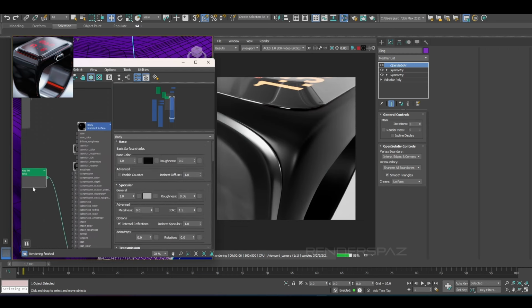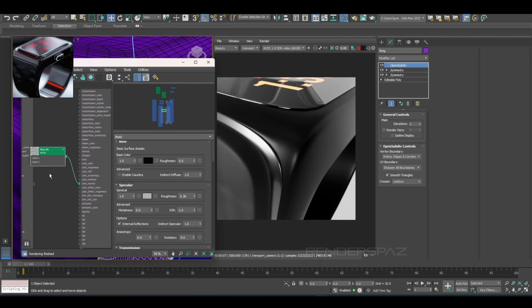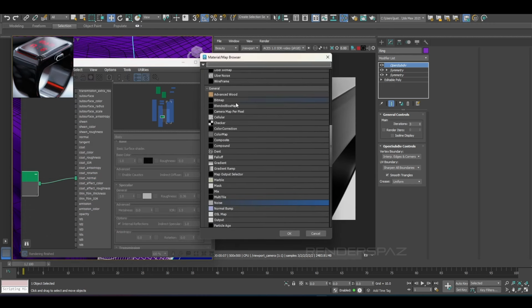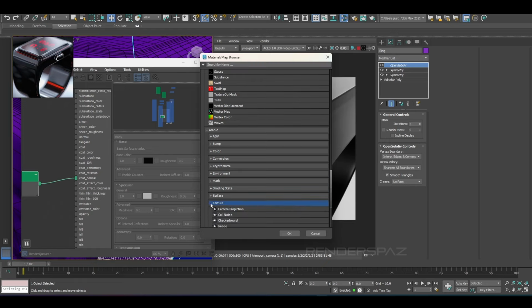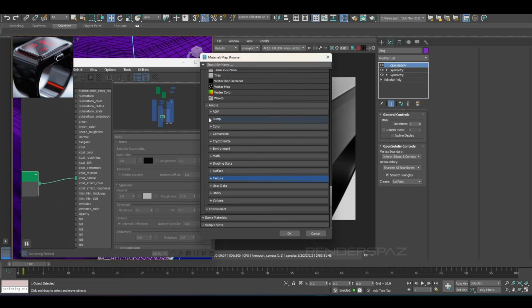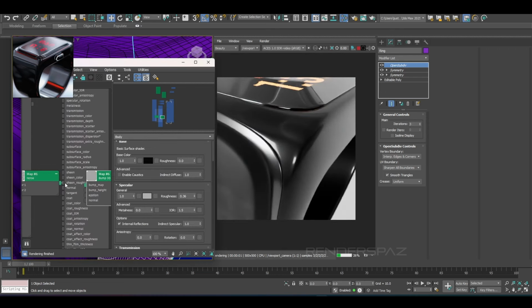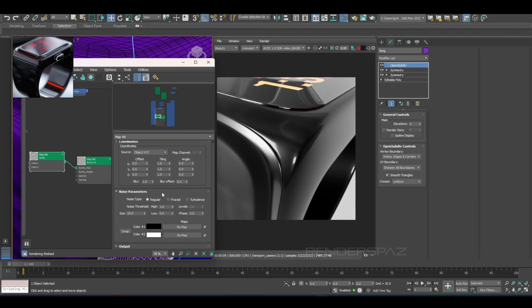So now what we just got to do is focus on getting a little bit of bump map to the surface itself, so it kind of looks more like it would be a glossy plastic or metal. You can have just a little bit of bump map to it. So we're going to apply a bump 3D map and just plug this guy in. Okay, I'm just going up. Let's get rid of this or hide that. And now we can actually see what we're doing.